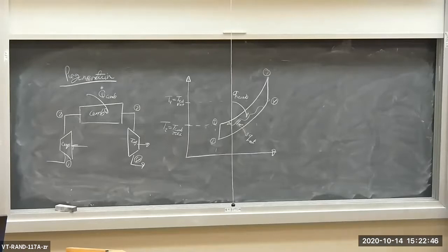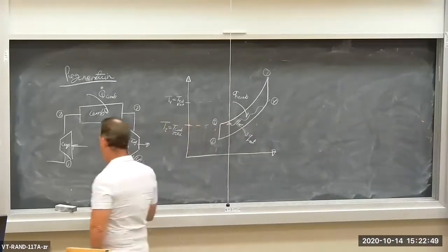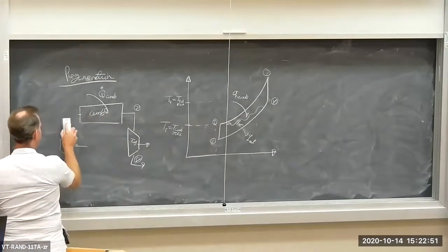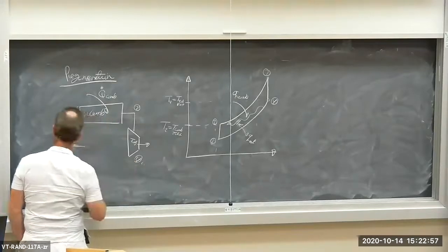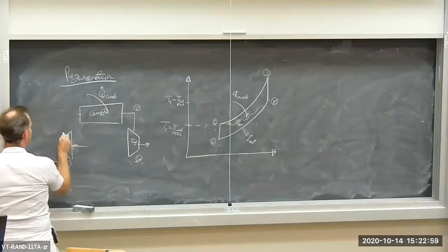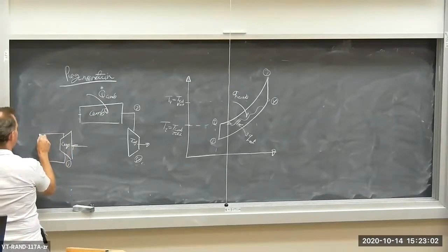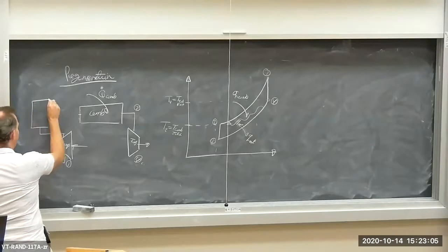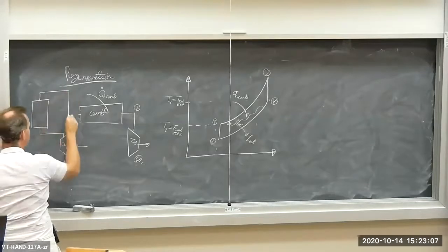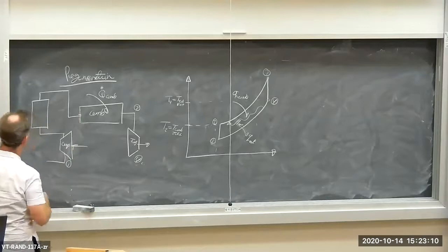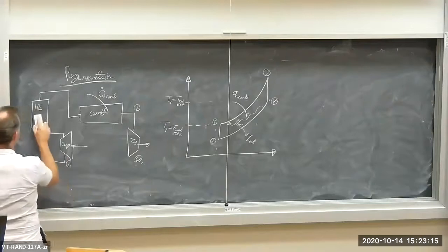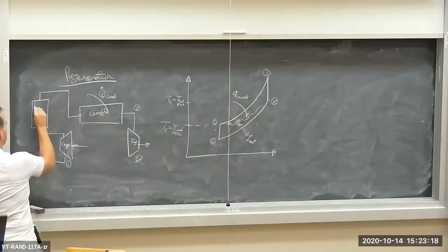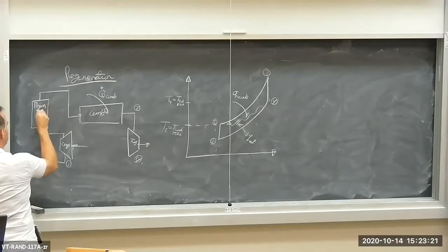Now, what's a way I could do that? Well, I can take the compressor outlet gases, air, and feed it into a heat exchanger, or if you like, a regenerator.